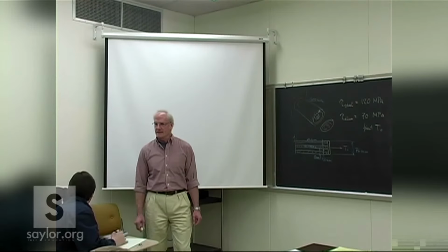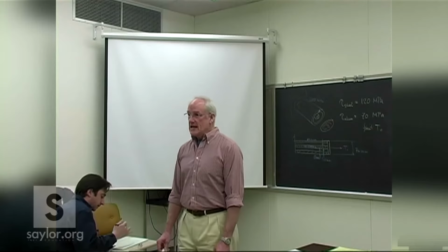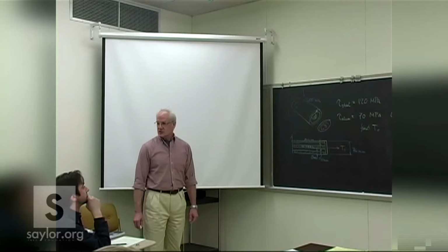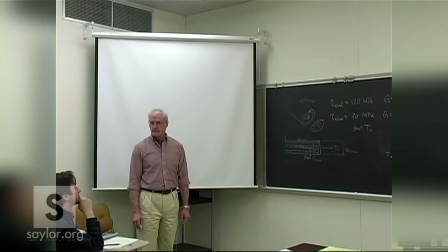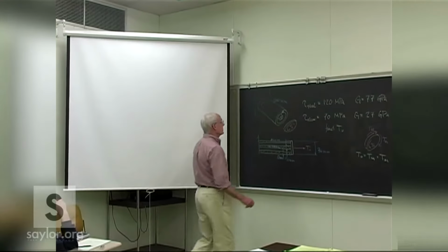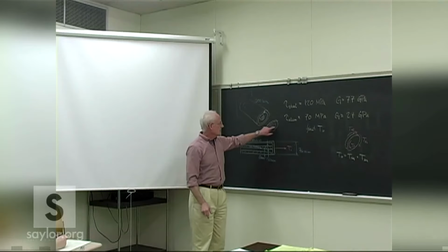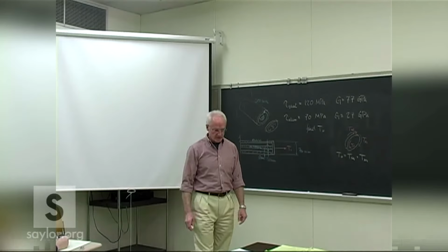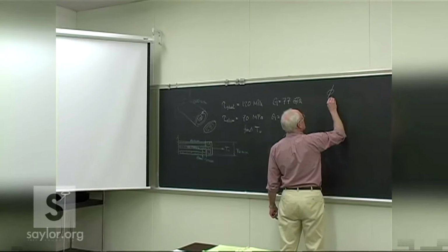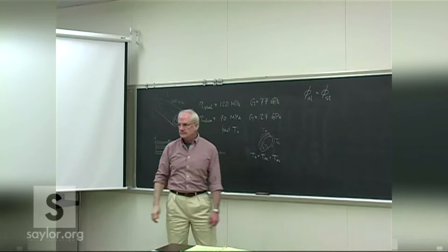Not really much change of length expected here. Yeah, the angle of twist is going to be the same on the two. However much one twists, the other is going to twist just as much. That again is on the assumption that this cap is rigid. So we can also use the fact that whatever angle of twist we see in one, we'll see in the other.